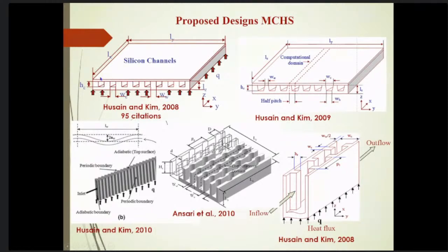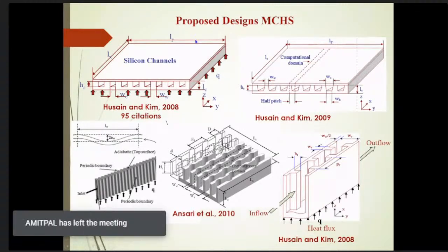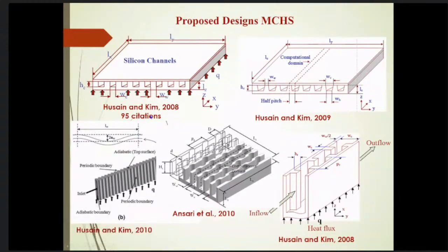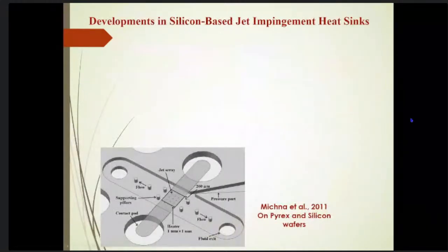So near the entrance a higher rate is achieved and at the exit a lower rate, and at the same time near the entrance the chip surface temperature is low, and at the exit the chip surface is high. So that makes a temperature gradient at the chip surface, and that is another detrimental factor for the chip life and durability, which we want to overcome.